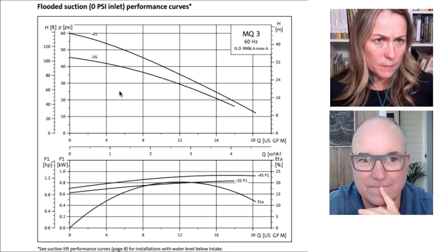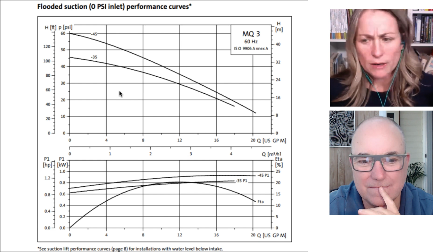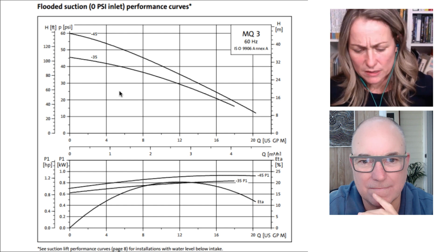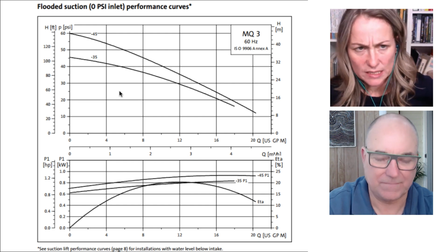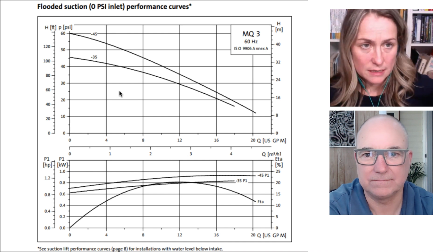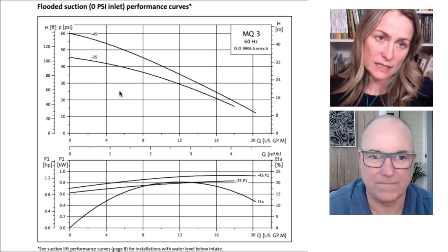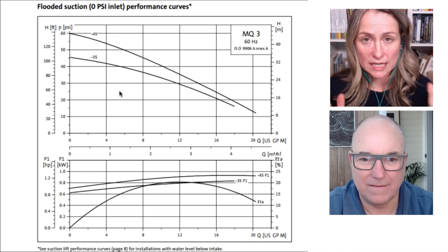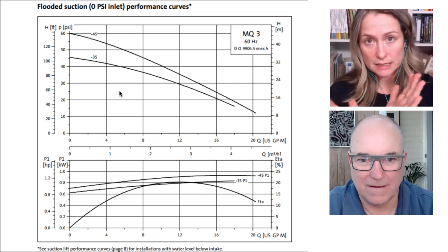So, what do you say, Peter? How important is it for designers in every situation to go through this level of detail that we did, in terms of thinking through the flow rate at the fixture, calculating the pressure head and then adding that to your pump head to come up with your total dynamic head, and then looking at a pump curve to see how it matches?